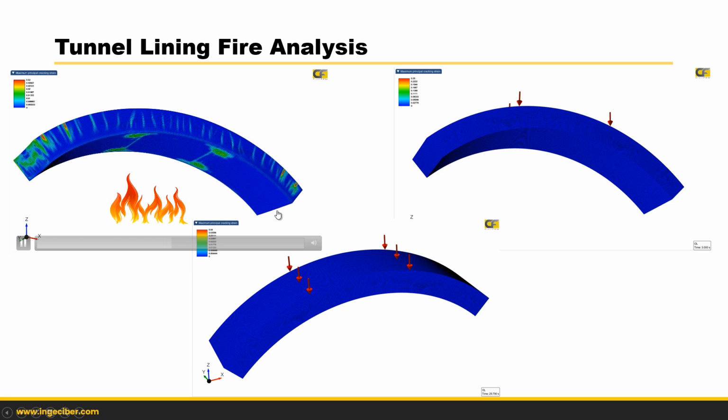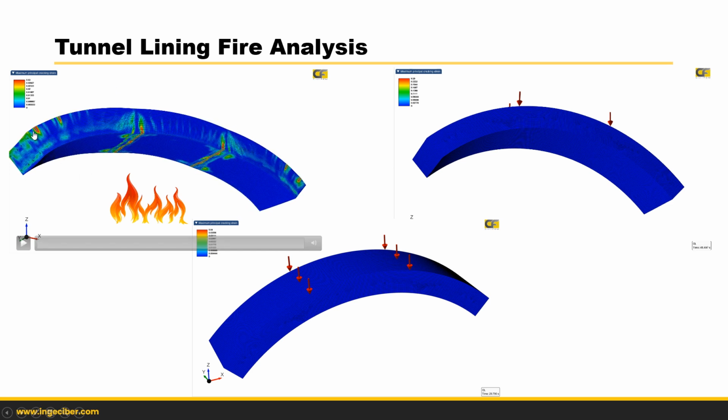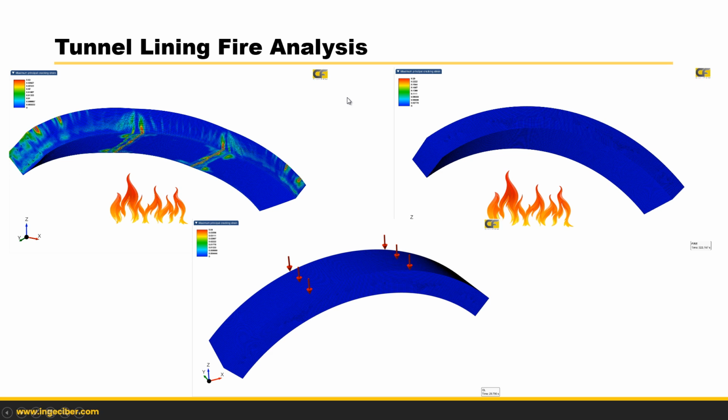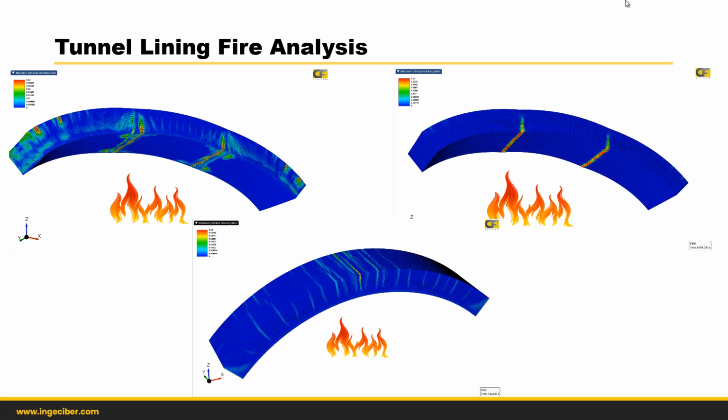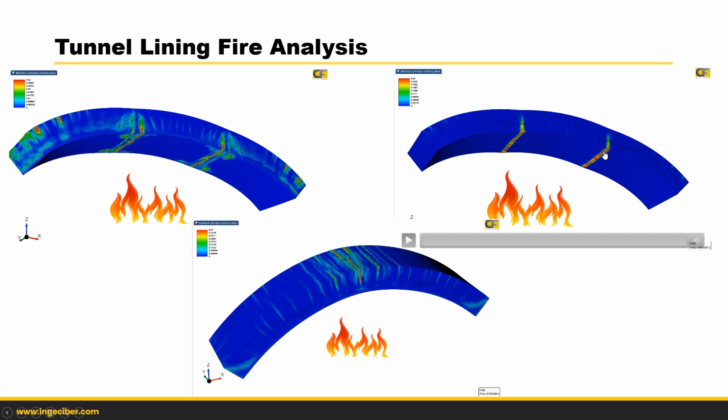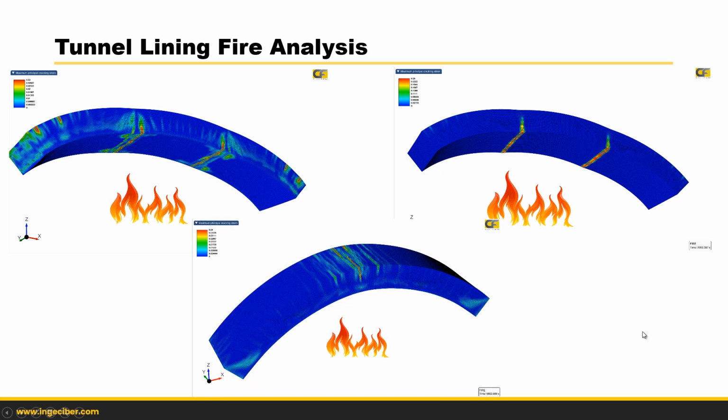In this case, it was flexible connections, where cracking is happening at 1/3 under the loads, and also in the supports. We have positive and negative boundary conditions. In the next one, on the right, we have another boundary condition, which is pin simply supported, and cracks only happen here. And in this other one at the bottom, we have completely constrained boundary conditions. With this completely constrained, due to the loads we have compression in these zones, and the thermal loads are generating cracks on top. So it depends on the boundary conditions.